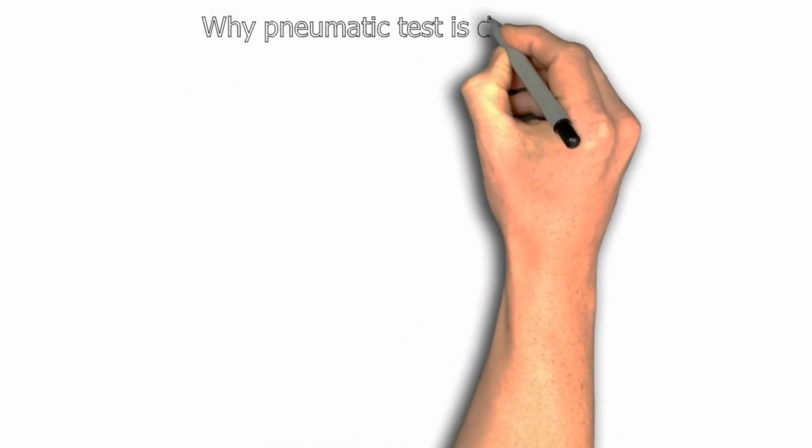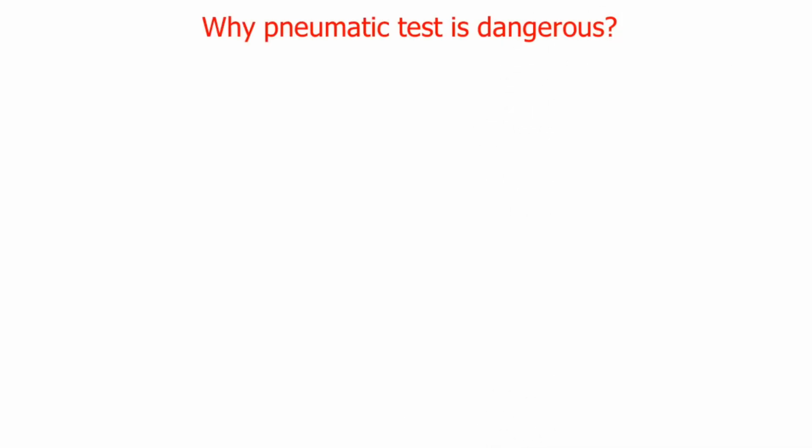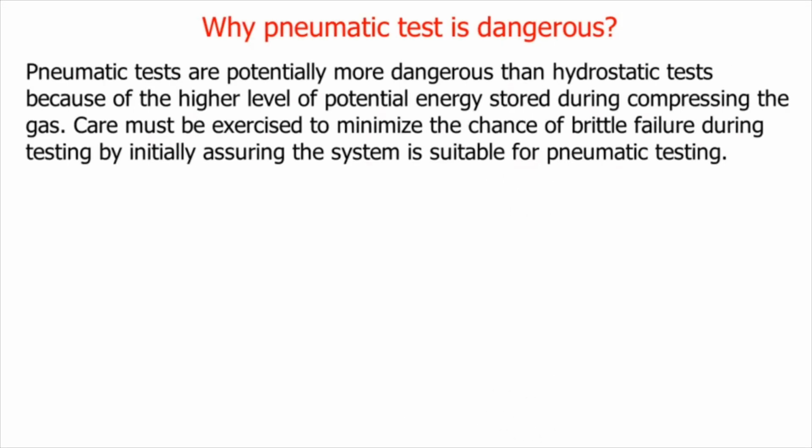Why is a pneumatic test dangerous? Pneumatic tests are potentially more dangerous than hydrostatic tests because of the higher level of potential energy stored during compressing the gas. Care must be exercised to minimize the chance of brittle failure during testing by initially assuring the system is suitable for pneumatic testing.